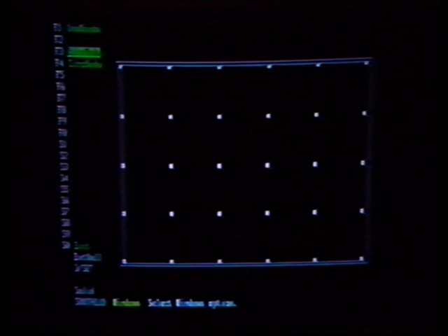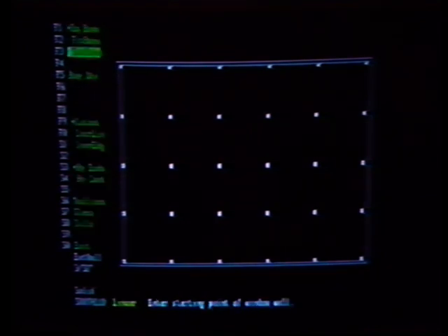And now we'll go back and put in windows in that wall by choosing the menu right below Walls, Windows. DataCAD AEC allows me to create linear bays of windows or circular bays of windows. Here I'll choose linear bays of windows, and just by specifying that I want 20 windows across this facade, equally spaced, I locate 2 points on the outside of the wall, and DataCAD AEC automatically breaks that wall, inserts mullions, and inserts the window glass automatically.